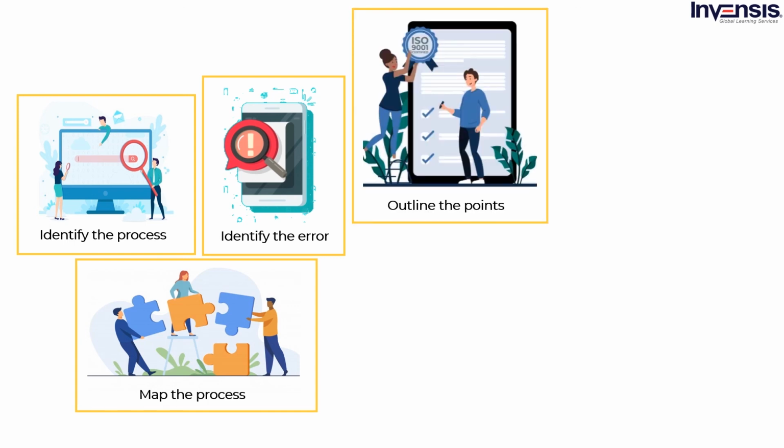Outline your options. Now that you've identified those errors, brainstorm ways to make it impossible for those errors to occur. You can do this by simplifying the steps so the action is simpler to perform than the error to occur, eliminating the step by asking if it is necessary and adds value, and implementing Poka-Yoke to make it impossible to create an error during the step.